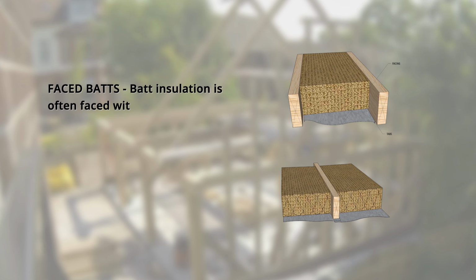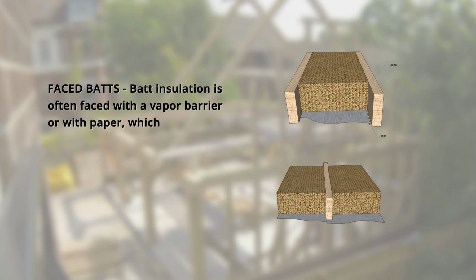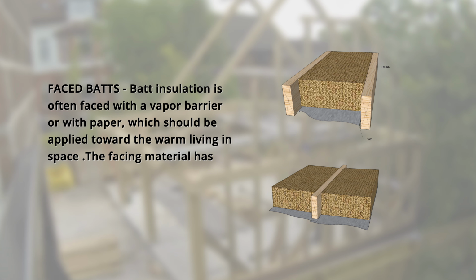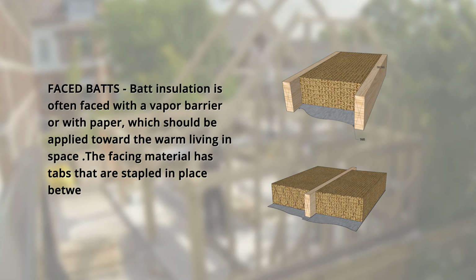Insulation. Faced batts. Batt insulation is often faced with a vapor barrier or with paper, which should be applied toward the warm living space. The facing material has tabs that are stapled in place between the studs.